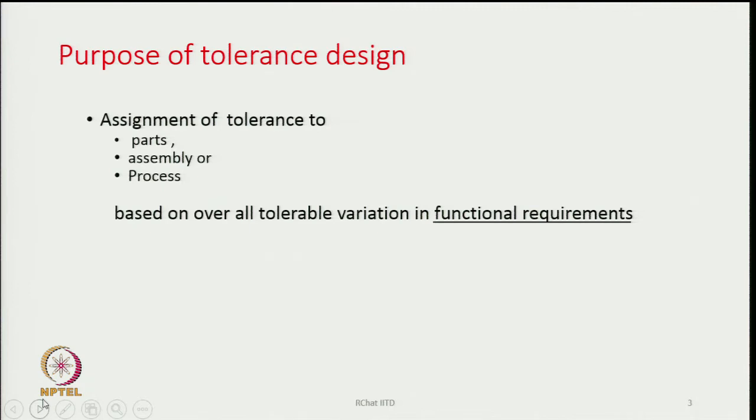So, these are different parts of the fabrics, and if somebody says that the nominal weight of this uniform or this jacket, whatever it is, is some value x, with a tolerance of 4%, 5%, 1%, whatever it is, then when we are trying to manufacture that product, it consists of so many different components, and we have to also now see how much tolerance we should give to those individual parts or components that will contribute to the total weight of that garment. It could be uniform, it could be jacket, whatever it is.